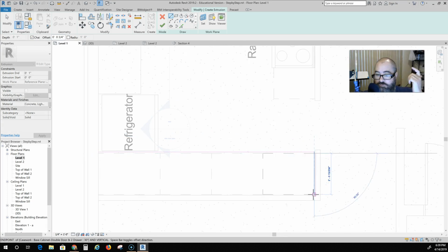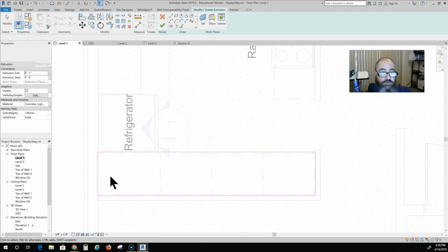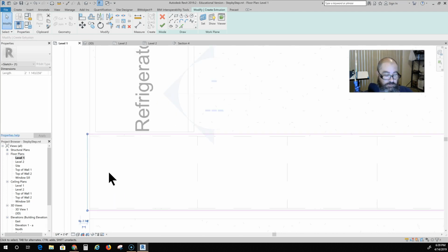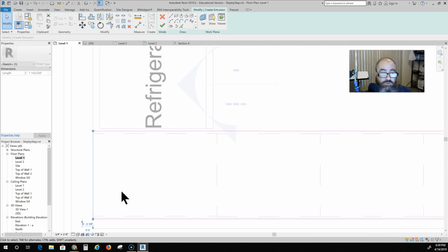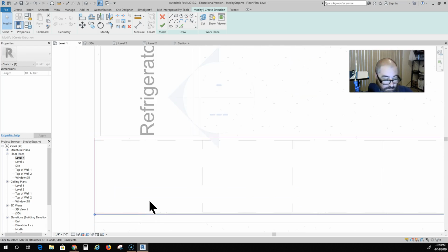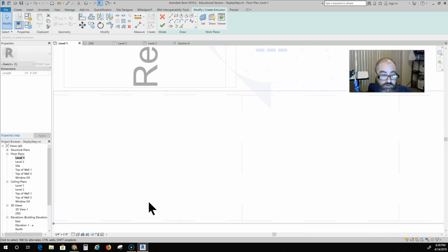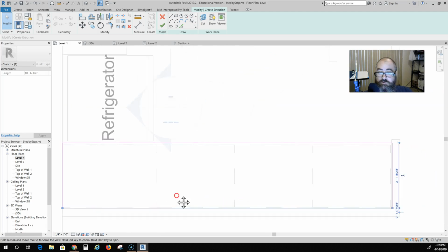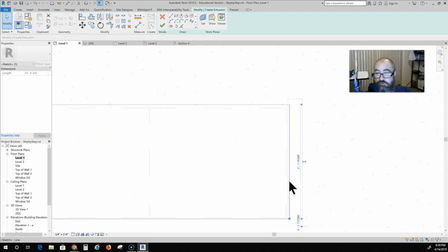And I'll remove the offset from basically every side except for that front side. So I really would have saved myself some work if I would have just manually offset the front instead of having to go back and remove the offset from 3 different sides.